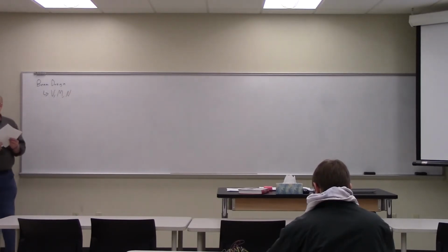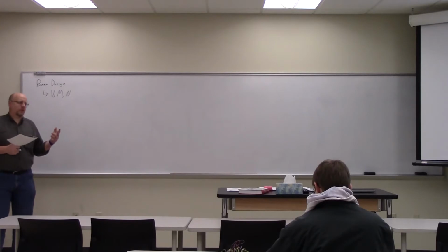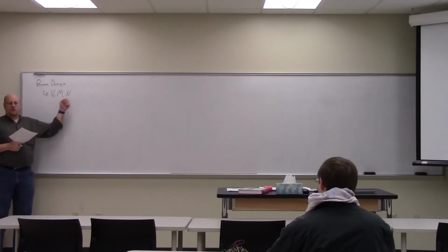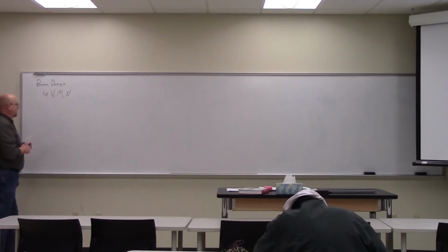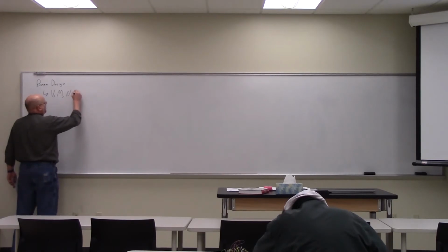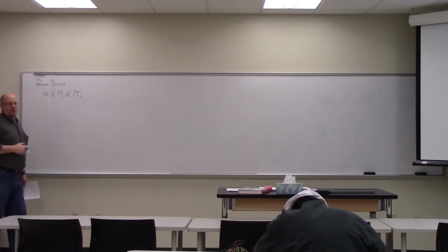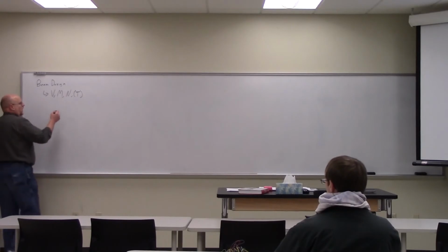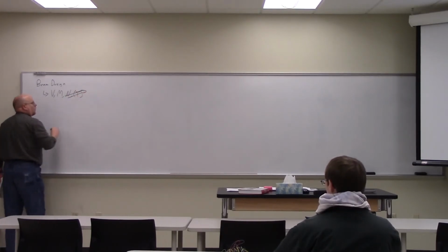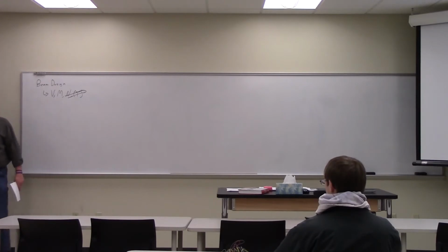Right, there are three internal loads that we typically concern ourselves with: shear, moments, and a normal load. Those are the three distinctive loads that we typically experience in a member. You might actually break moments into torsional moments and bending moments, if you wanted to include them separately. But in most applications, these two are going to be negligible. The normal load and the torsional load are typically not going to be all that great, particularly if everything's functioning as it's designed to function.